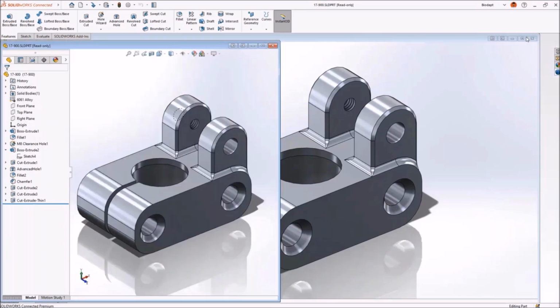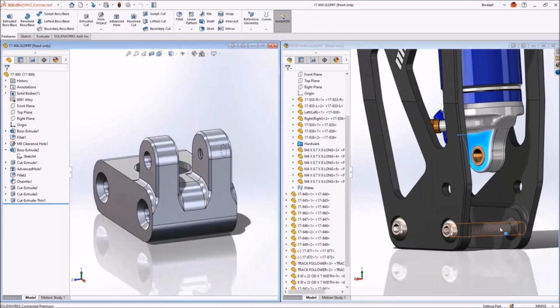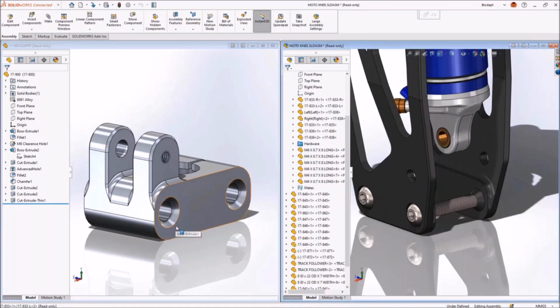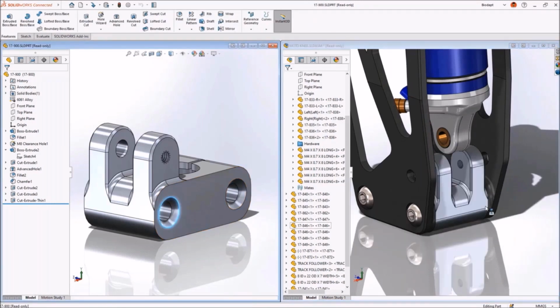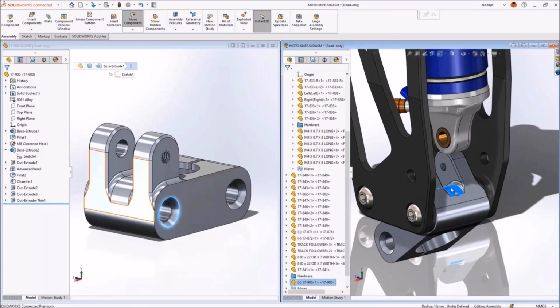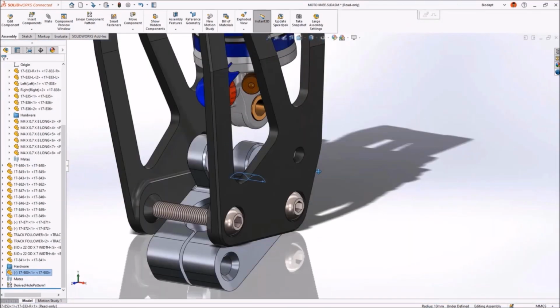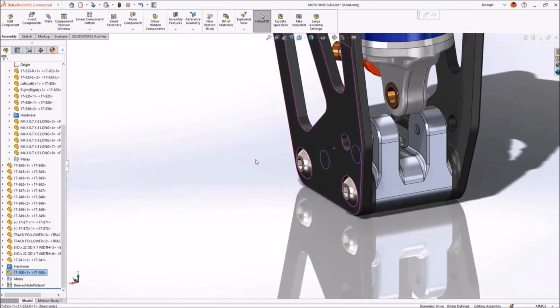So let's insert this new lower bracket into the vMoto assembly. So here we will be using SmartMate features, again a functionality of SolidWorks. So directly by dropping it into the assembly, it will get snapped to the mouth board assembly. It will get coincident and concentric mates along with that pin. Let's close that part. And now if you see, the rotation of that lower bracket is still free. Let's snap it to the pin using the SmartMate feature by simply pressing down the Alt key.